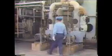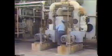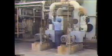When the operator has selected the recirculating pump to be used, he closes the drain valve and opens the suction and discharge valves on that pump. He also makes sure that those same valves are closed on the other pump. This is known as lining up the valves.